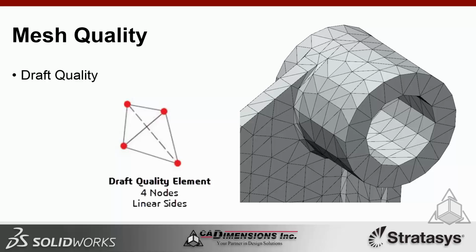As you can see here, with draft quality mesh, the elements don't do a great job of matching the real geometry. The holes and nonlinear edges end up being oversimplified and really faceted. I could go ahead and shrink the mesh down quite a bit and get a better resolution in the areas where it's faceted, but as you can see in the next slide, that's not going to be necessary.